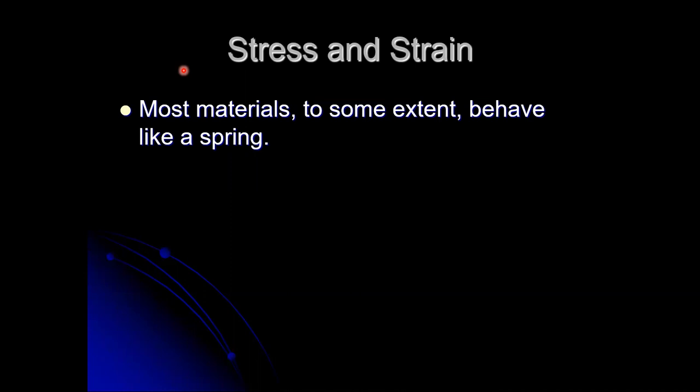The internal equivalent is what we call strain. Internally, we can think of how much each inch of the material grows. So maybe each inch becomes an inch plus 5 thousandths. Now, how much the overall member grows depends on how many inches are involved.